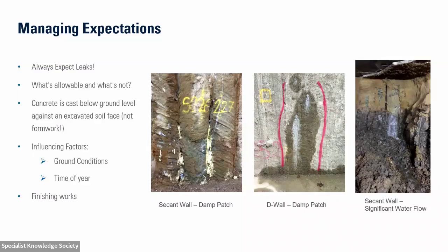So again, it should be considered as part of the design considerations, I think, that you have around how you're looking at embedded retaining walls and what water retention you need at the end of the day. So they only provide a certain class of water retention. And I think if people's expectations are managed around what walls look like when they excavate, they're happy with it. If people are expecting a perfect wall finish, they get a bit disappointed when they start digging down.